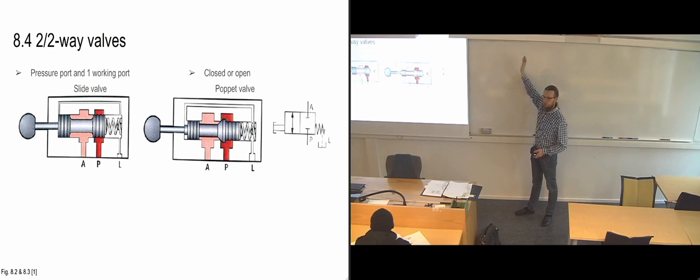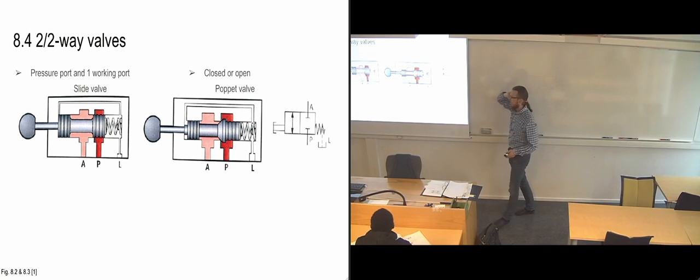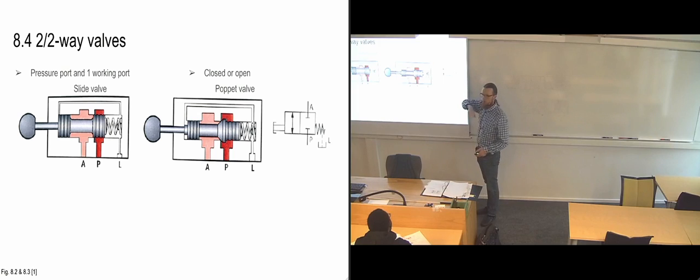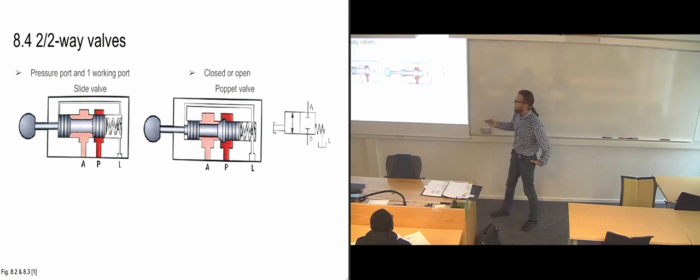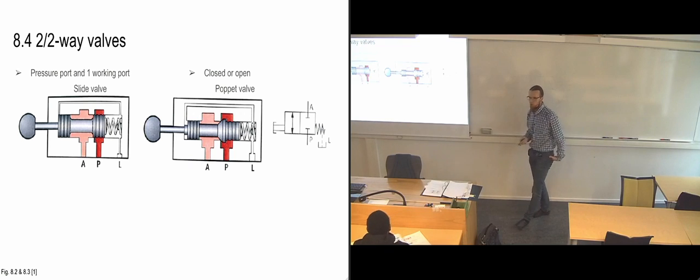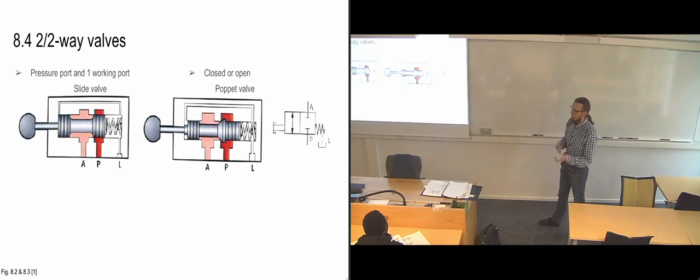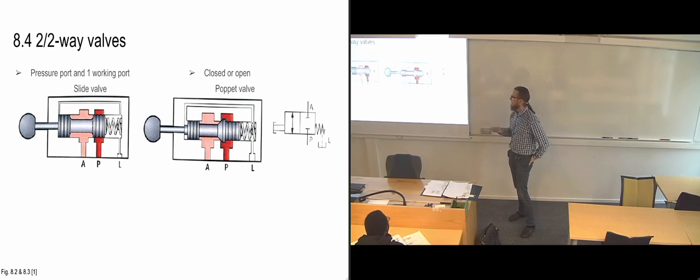And the single-acting cylinder also has a spring that's going to push it back if we stop it. So if we just cut off the flow from the pump, then the spring is going to act on the cylinder, and it's going to push the flow back this way. So that's why it's going both ways in this case, because we don't have a direct return to tank on it. Most likely you would have another valve system further back that would allow flow to return to tank somehow, that you would cut off the pressure from the pump and allow flow back to tank. It depends on your system. If it's just a very simple system, it might be that you only have this one.